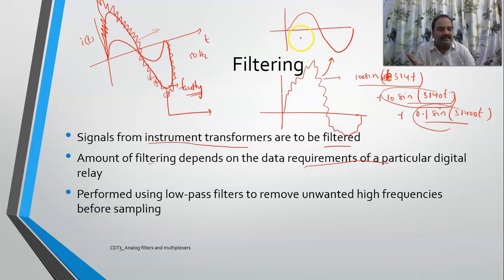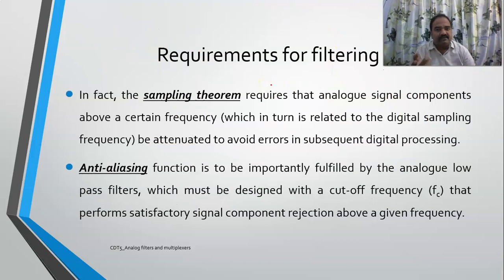So I may get a signal which is closer to my power frequency, or it may include only sub frequencies of your power frequency. That job will be taken care of by the low pass filter. If you use a low pass filter, the biggest advantage is that you can get an appropriate, close to accurate signal, which you can then analyze to get the desired data. Right?